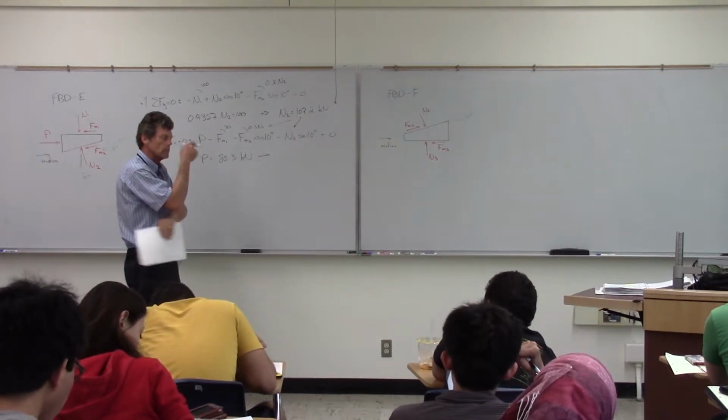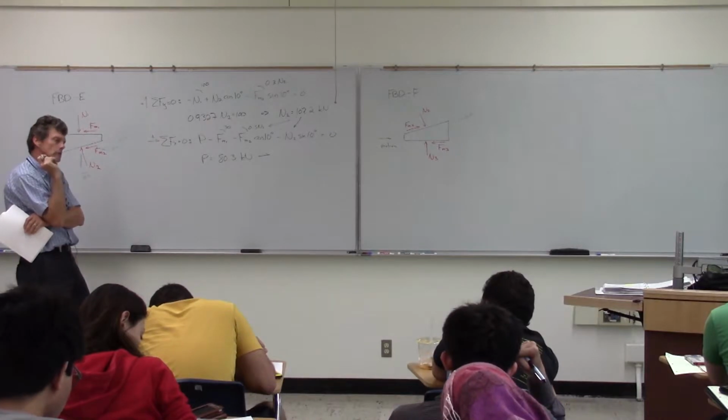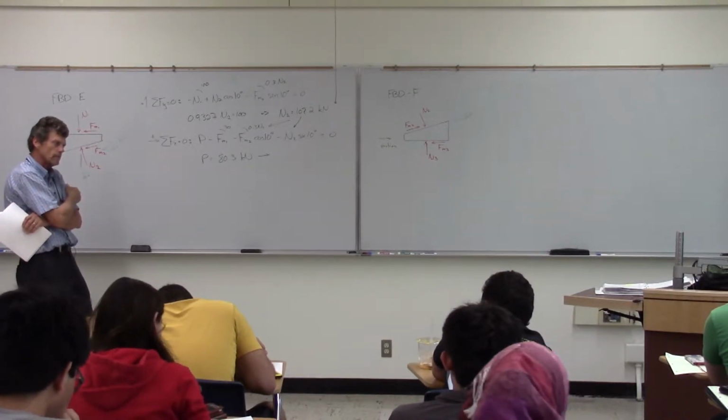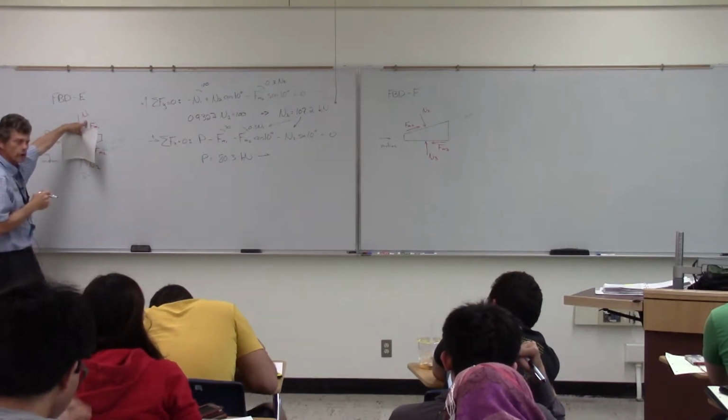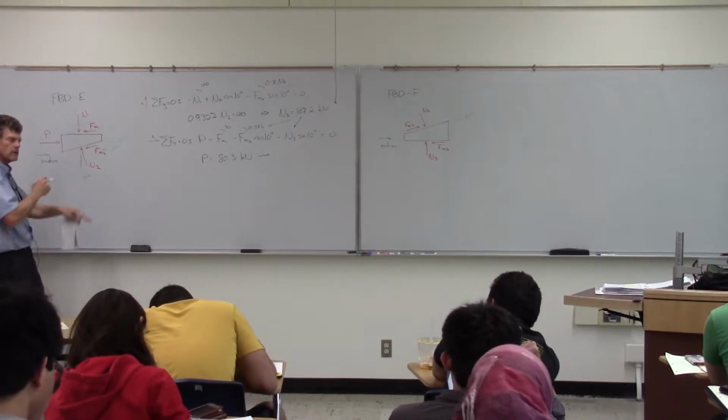So in reality, though, the weight would have an effect on it, wouldn't it? It's creating our normal force, yeah. It's creating our normal forces on those wedges. Think about this one. N1 was 100, right? Because the beam was sitting right on top of it. And because of the angle here, this has to be a little bit higher.